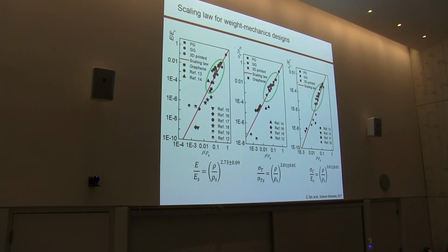Yes. So once I do that calculation, I take the building block as graphene. That's already the strongest material we know in the world, and its density is light enough. Carbon is not very heavy. So I got disappointed, because if graphene cannot do that, other polymers probably cannot, because they cannot be stronger than graphene. Maybe there are materials lighter than graphene, but the design space is not very huge.